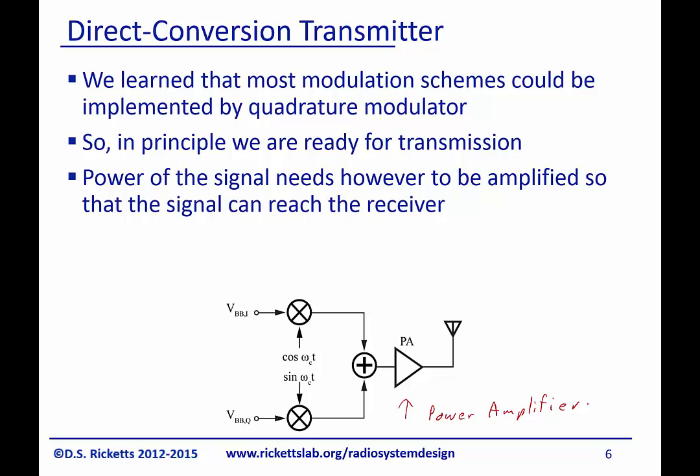And that leads to architectures in power amplifiers that aren't like small signal amplifiers. In particular, many power amplifiers can be switching amplifiers that have quite a bit of harmonics, but they provide very high output efficiency and output power, and so there's always a trade-off that's there. We'll discuss how to build a power amplifier in one of the last modules in this course.